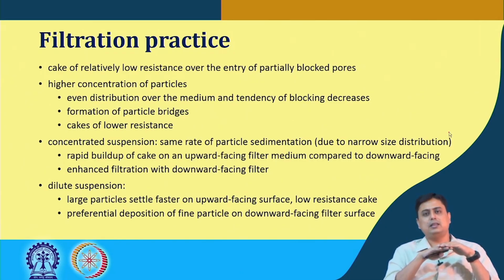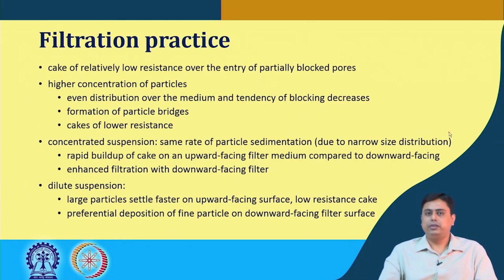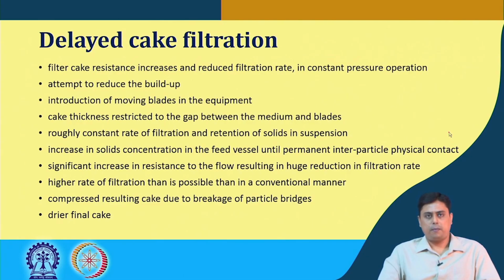In this case the cake resistance will be much larger than on an upward facing surface. So the orientation of the filter surface or filter medium is critical and has to be considered, along with the particle concentration in the suspension or slurry. During the practice of filtration, these things have to be kept in mind.